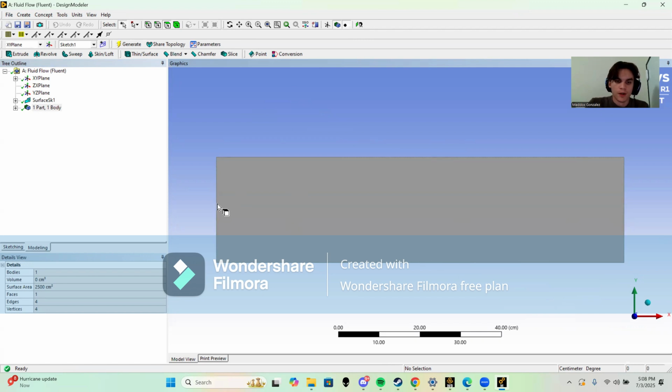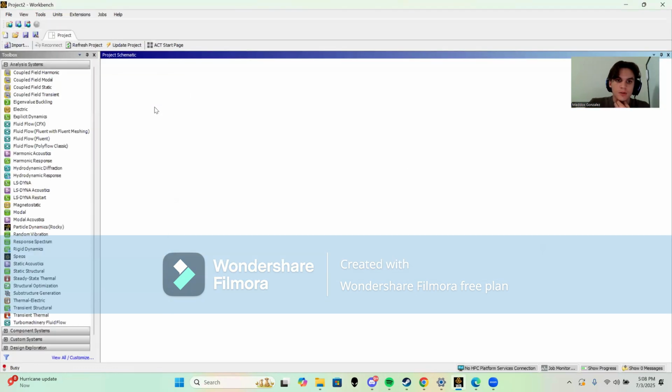And then by left control and left click, you can click on each side again to name each side. So I named my left wall inlet, my right wall is my outlet, the bottom wall is the flat plate, and then I named my top wall as my symmetry for meshing. So that's it in Sketch. We don't have multiple sketches this time. So we can close out of that and go to meshing.